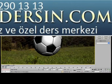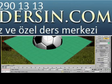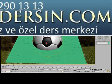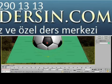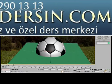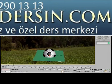Can you see the grid that we have here? Okay, we're going to drag a plane across this grid. So let's go to the command panel, select plane, and just drag it across the grid like this. Don't worry about the size. Let's adjust our plane by using the orbit tool at the bottom of the screen. We can turn it round. Use the pan tool to bring it down. And use the middle roller on our mouse just to zoom out a little bit. And we'll carry on bringing it down closer to the ground, like this.